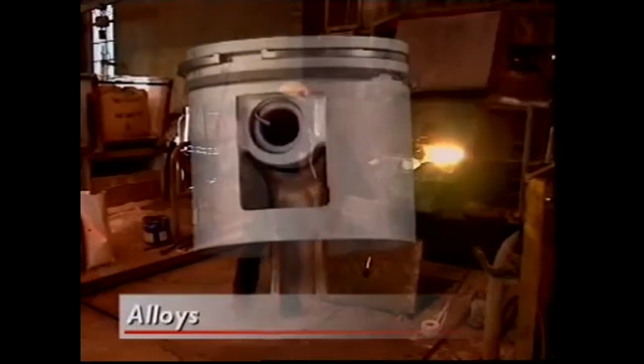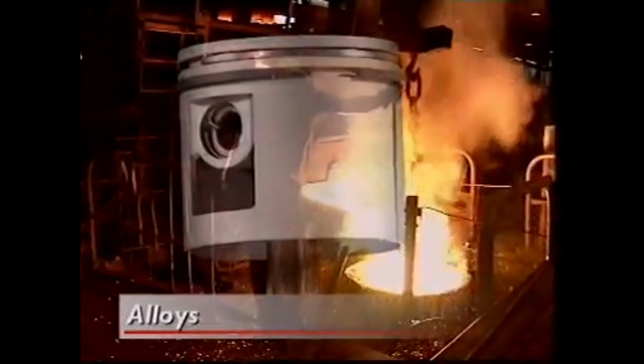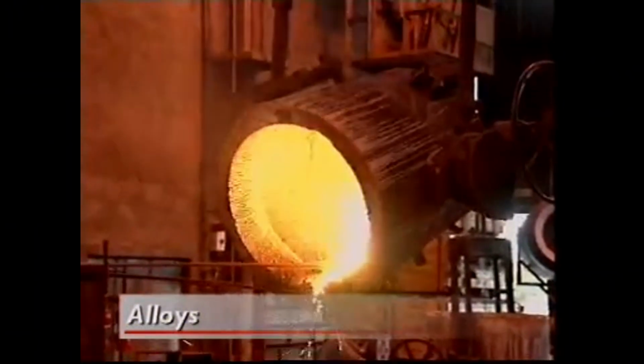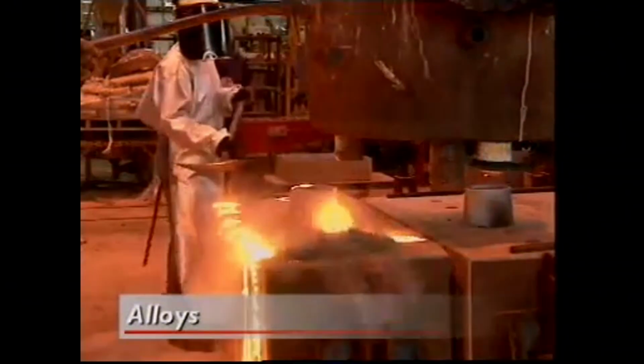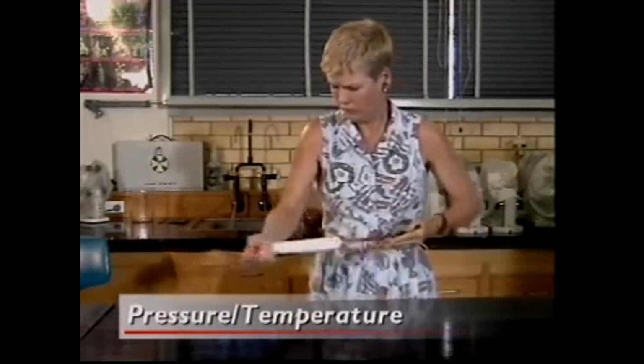An alloy is a combination of materials to make a substance that has properties that are different from the original materials. Aluminium by itself is too soft to stand up to the pressures a piston copes with, but if it is mixed with other materials, alloys are produced that are ideal as pistons. In the same way, different steels can be made with a huge range of properties by changing levels of carbon in iron. Alloys can be designed with exactly the properties a particular part needs.